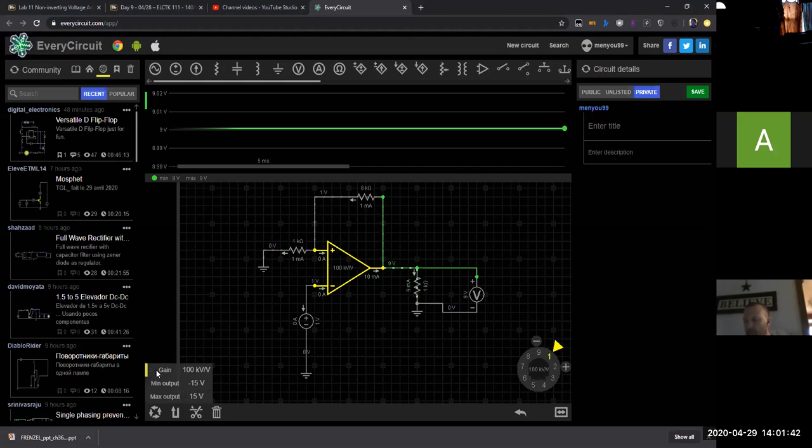And then think of this as your gain factor. And watch that. See how it's that K there? So this is 100,000, which is very typical. That would come more from the spec sheet, but this is the 741 model. You could say the LM741C, which is probably the most popular model out there.